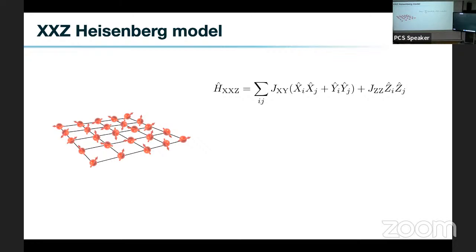We can make it, but the scalability will not be good. The idea is just making a capacitor between the qubits, which induces the dipole coupling between them. The capacitor can be considered just like an electric wire. So we make an electric wire between them, and between them, and we can make an electric wire by jumping over here. In this way, we can make all-to-all connectivity, but this is not a scalable way. Okay. Or there is another approach using the parametric scheme, but I will not talk about it now.